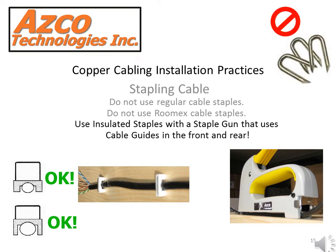Stapling cable. Do not use regular cable staples or staple guns. Do not use Romex or electrical wire cable staples. Only use insulated staples that have standoffs to prevent the staple from damaging the actual cable itself. As you can see here with the Azco AZS667 staple gun, not only does it use the insulated staples preventing the cable from getting damaged, but also uses a cable guide in the front and rear of the stapler so the kickback doesn't damage the cable on the rear.